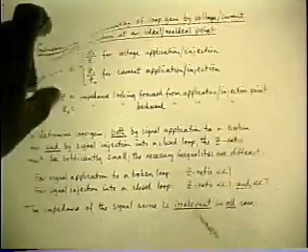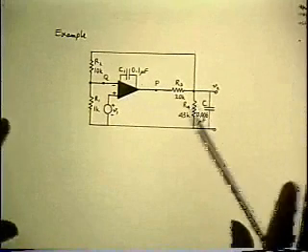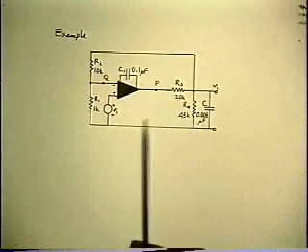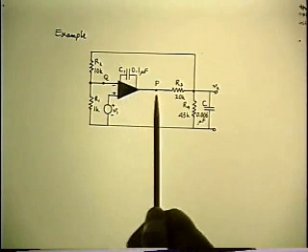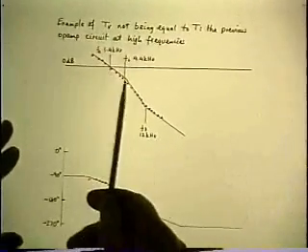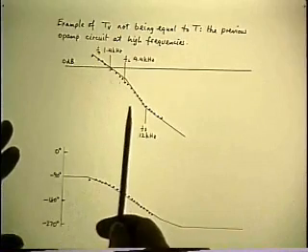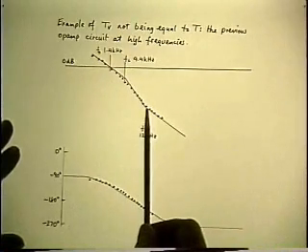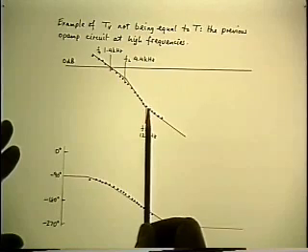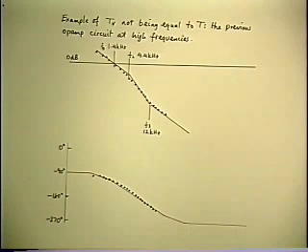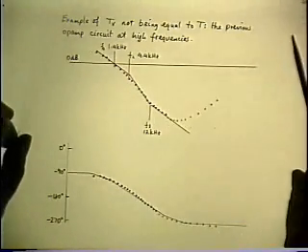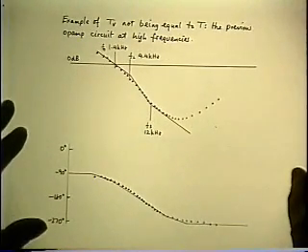And just to drive that home even further, let's go back to this example we already used initially to introduce the technique of loop gain measurement by signal injection. Here's the circuit. We chose P as the injection point. We predicted a loop gain that had 2 poles. And then we made measurements, and we discovered that there was a right half plane 0. And then we found out where that came from, and we're satisfied with that and say, well, fine, everything's all right. Unfortunately, if you simply continue the measurements up to higher frequencies, everything is not all right again.